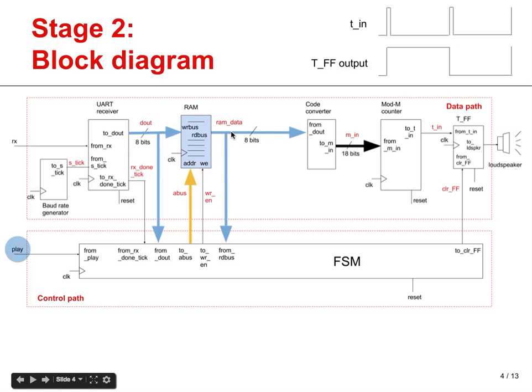The output from the memory comes from the so-called read bus, and in this case we do not need a read signal because whenever we address any given position, the corresponding content will come out automatically. As you may know, the read signal is essentially needed whenever we need to avoid a conflict in the data bus, but in this case we do not have more than one device trying to access the same bus, so we do not need a read enable signal.